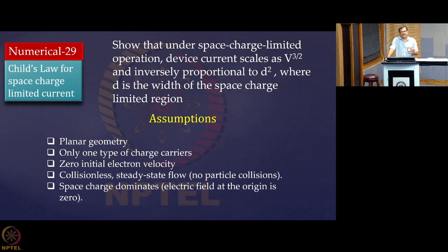When the electrons are emitted, because so many electrons are surrounding, they are emitted with almost zero velocity. Then the variation in potential near the cathode is almost ∂V/∂x = 0, if x is the axial direction. So V is 0, ∂V/∂x is 0 at t = 0, at x = 0, and then the space charge is moving and constituting the current. So in those cases, the V-I relationship is not linear.